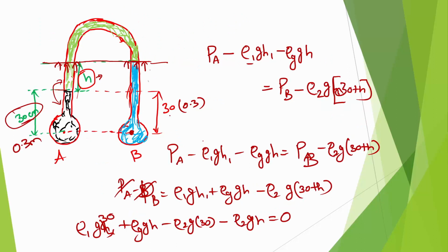So we have found out the value of H. So when you have the pressure at these two as the given value, which are equal, then this will be 20 centimeter. So this is the answer for question number 1. Again, we have derived the formula at pressure for 2 at the top level, equated it, simplified it, and got the value. The only place where you have to be careful is converting centimeter into meter, which you have to do.